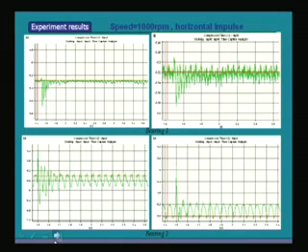Then these are typical time domain signals, especially this one. If you see, we have given an impact to the rotor through an impact hammer. So you can see there is this impact and a slight decay of the signal takes place, and then the usual periodic signal. But in this region, because of the impact, there are transient components. So we were using this for finding the damping in the system using the impact hammer.